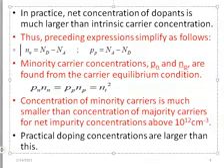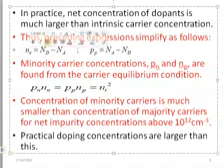So in each case, the minority carrier concentrations are Pn or Np. If you look at this one, we said we introduce donors more than what? The acceptors. Therefore it is N-type. So in this case, the minority carriers should be Pn. It is N-type, but still we have holes, because whenever temperature starts rising, bonds will be broken and definitely holes will be present, though they are much less than the electrons, and therefore they are the minority charge carriers.